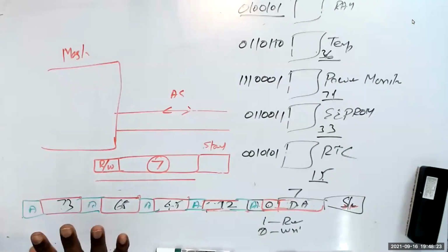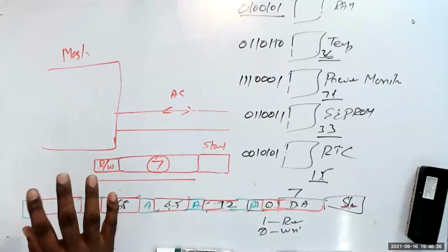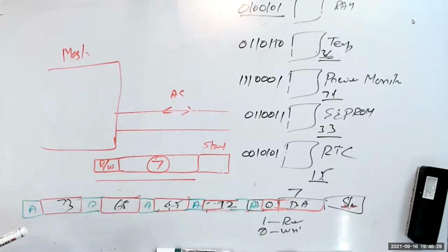There are two standards, but forget about that, somebody will get confused. Suddenly you said 10-bit. We don't even understand I2C, so don't bring in the other standards. If there is no acknowledgement, that means the device is not there. Then it will tell you that it is unable to write. You are the software, you are looking for the bit. You know that after sending 8 bits, you look for acknowledgement. If you don't get acknowledgement, the device is not there. Sometimes you see 'unable to write' like that, because you don't get acknowledgement.